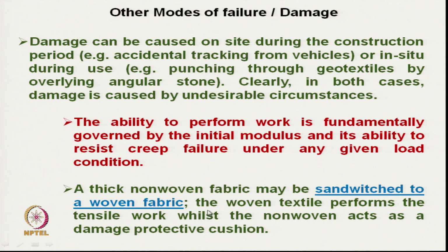So, a thick non-woven fabric may be sandwiched with woven fabric. The woven textile performs the tensile work, whilst the non-woven acts as damage protective cushion.